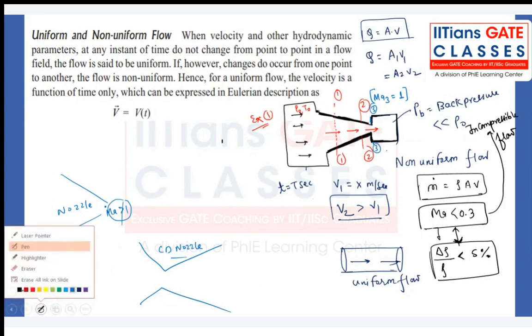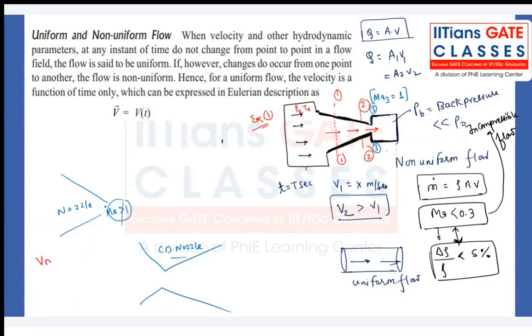Perfect, perfect. So that is the reason. Here we are giving a disturbance with respect to the fluid. Whatever the disturbance velocity is, or pulse wave or sound waves which are traveling, telling you the message that the back pressure has been reduced, you please try to increase the velocity, right? But the moment Mach number is equal to 1, what will happen? Velocity of disturbance minus velocity of the fluid.